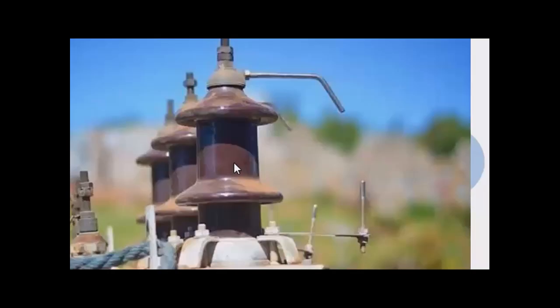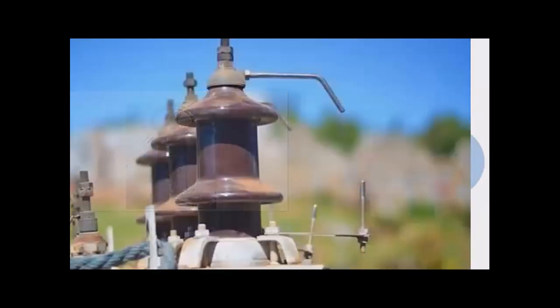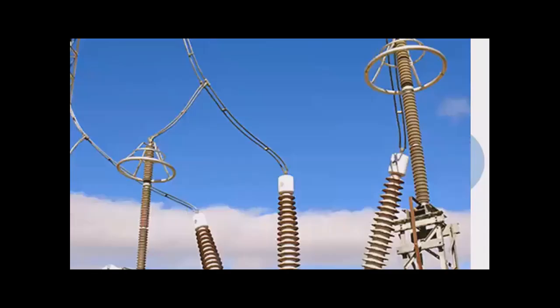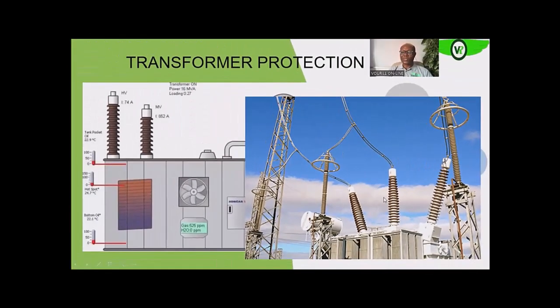That is how the surge suppressors or surge arresters in bigger units work also. These are the surge arresters in bigger units. So it's the same thing. Once there is a spike, it causes the breakdown of the insulation between here and the ground that it is connected to. And then instead of it going into the transformer, it just flows into the ground. So these are the surge arresters. We have three, one for each of the phases, for larger transformers.